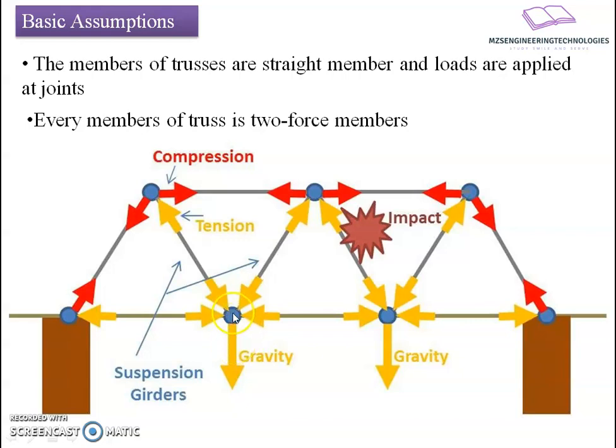If, instead of this, the load is applied on this end, what will happen? This end will now get stretched, and suppose the load is applied in the horizontal direction, likewise this will now stretch, and the members which were in compression for the initial case will now act as tensile members, under tension, so they will be subjected to a tension pull. A pull and push action, and reversal of this pull and push action, will be there within the members.